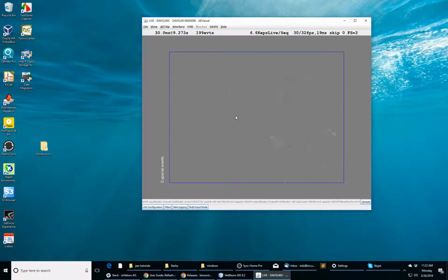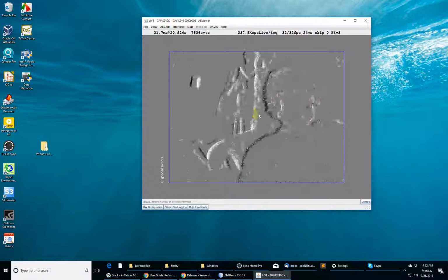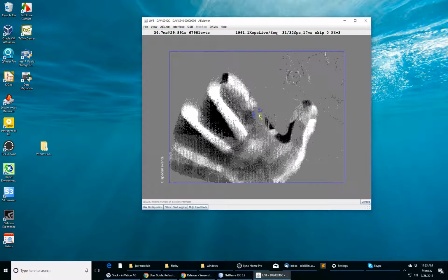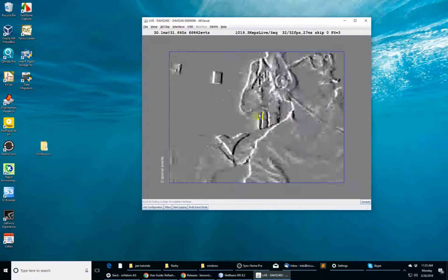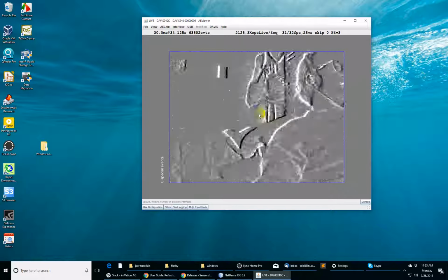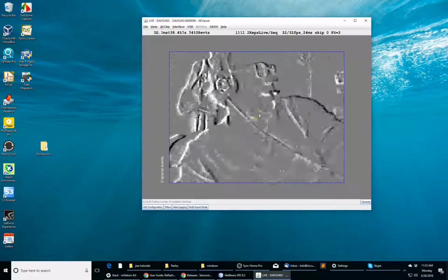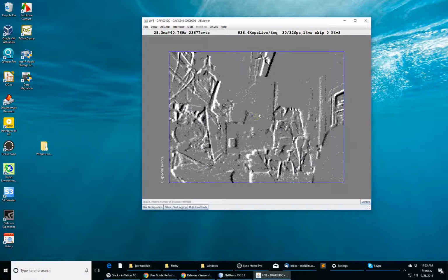Okay, I'm back. I managed to reflash the firmware on this Davis240C. So now I see that it has appeared here as Davis240 serial number 96. When I reflashed the firmware, I had first managed to reflash it as a DVS128. So there was quite a song and dance erasing that firmware and getting the correct firmware onto the camera. So here I am. You see the DVS output with Hakeem Olajuwon in the background, and the usual scene of our office here.